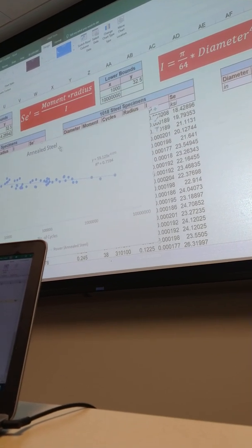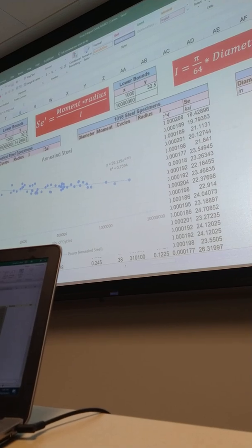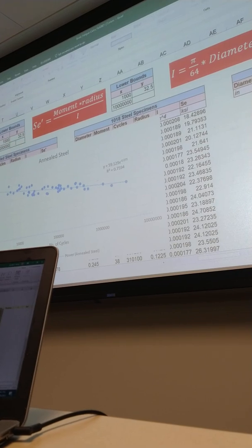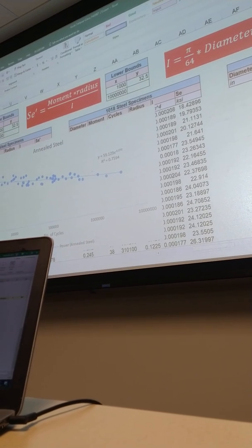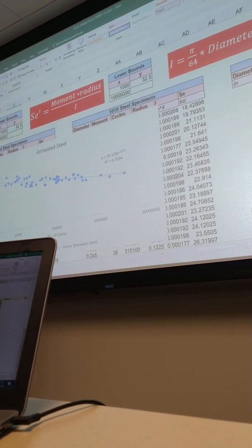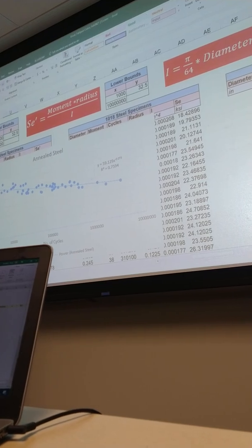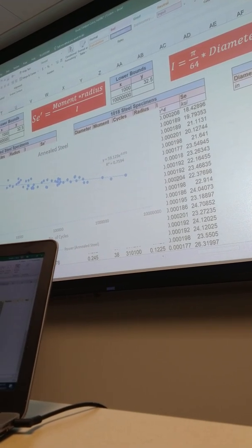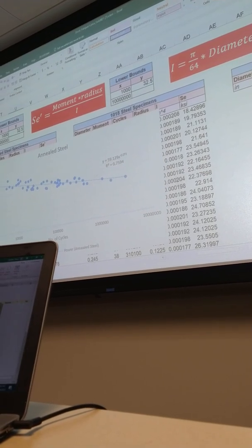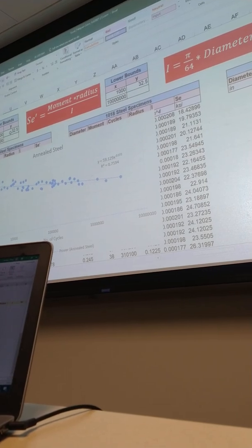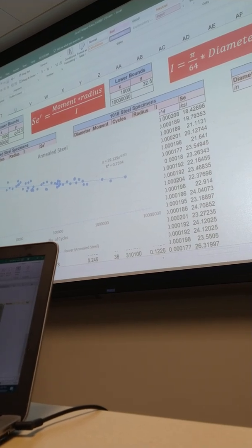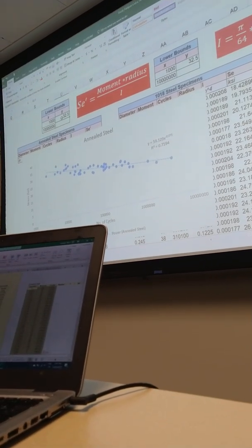Okay. We're going to create our lower bounds. You're going to start with 1,000, and I think this is 10 million. I just recommend using these numbers. These numbers are based off of your stress being in KSI, so you need to make sure your stress is in KSI before using those two numbers. And then you start with this guessed value. I know it's going to be 32.5, so I already have the guess going. So 32.5 is a good guessing value.